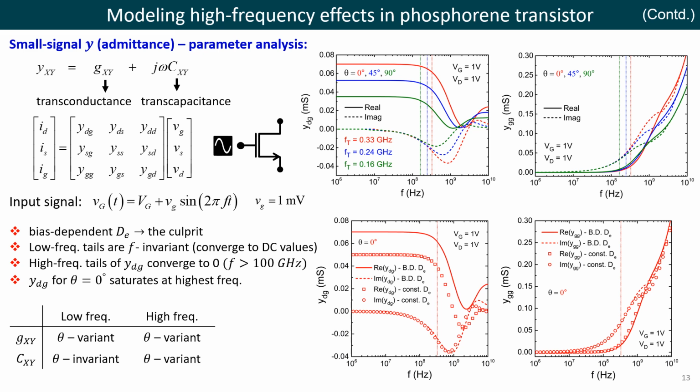Although several analytical treatments for the small signal non-quasi-static models have been proposed for conventional transistors, in our case, the bias-dependent character of electron diffusivity actually hinders a continuity equation-based derivation of closed-form Y-parameter expressions. Therefore, we have treated the whole problem numerically.